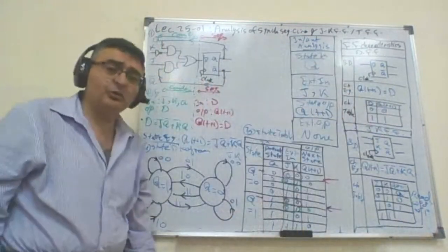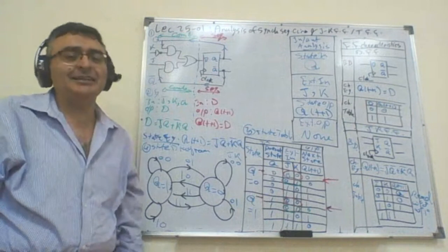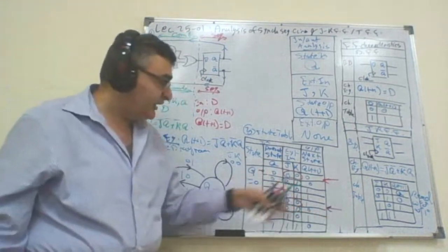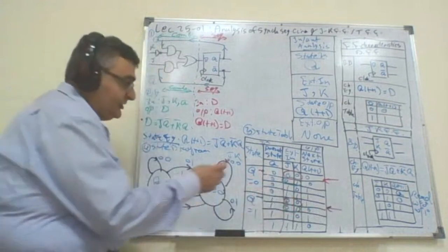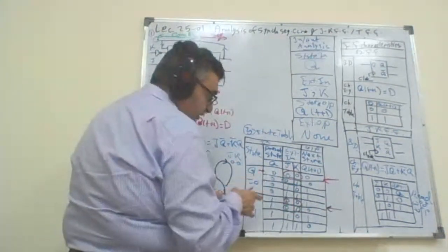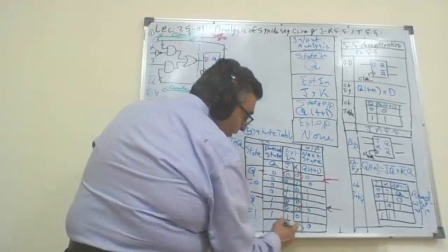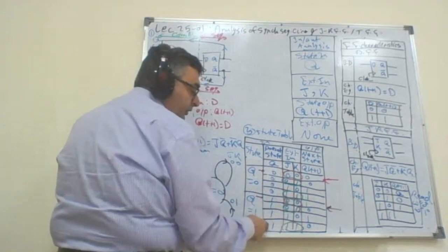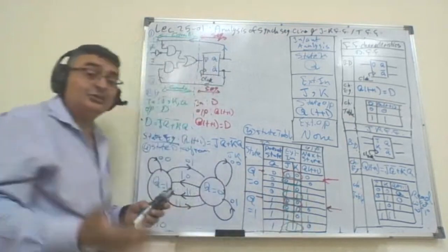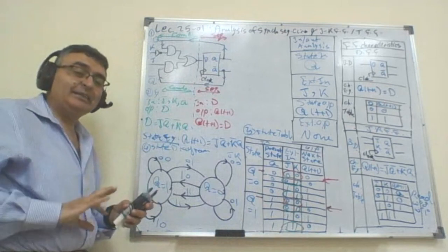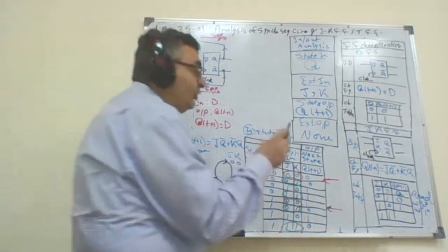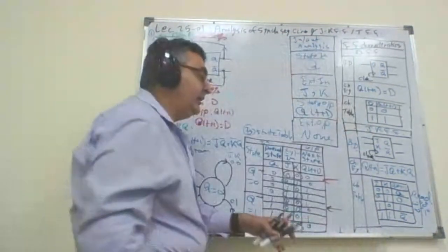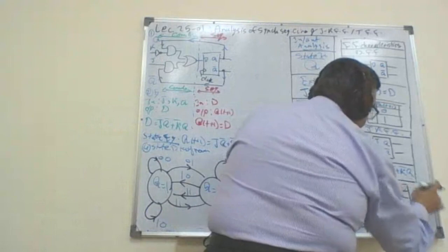In the SR latch, we have what's called the forbidden case. Do we have forbidden here? The answer is no. There's no forbidden here. Actually, here, when I have both J and K equal to 1, which is this case, you see it here, 1 and 1. If I start with 0, I end up with 1. If I start with 1, I end up with 0. So it is flipping. I have here the output equals Q bar, which they call toggling. Toggle.